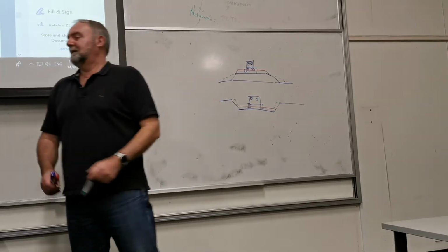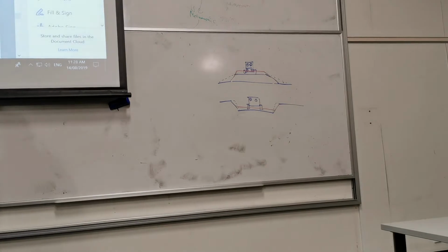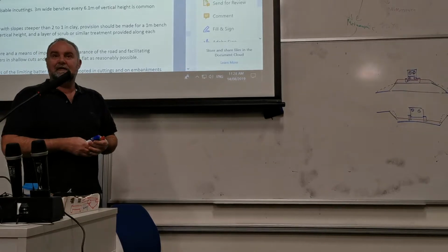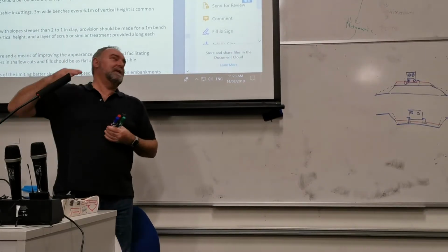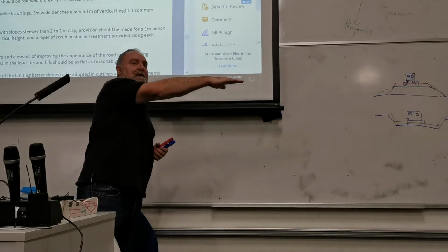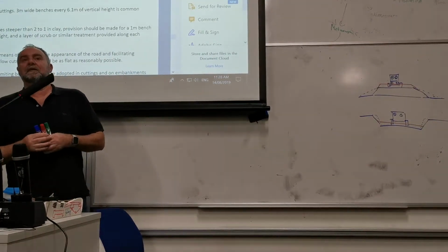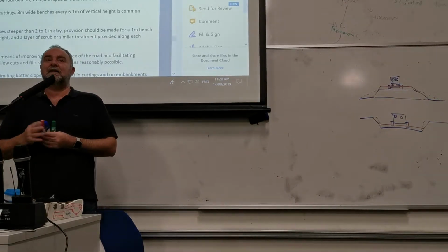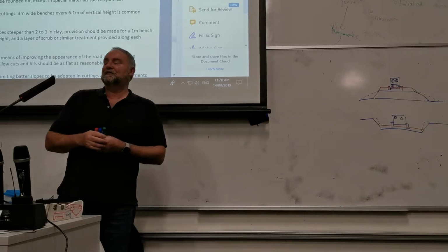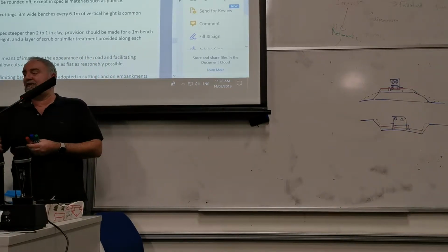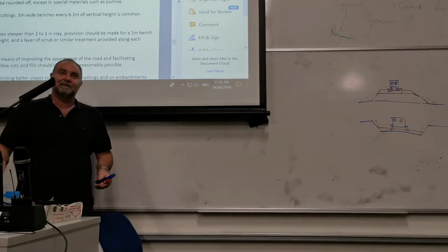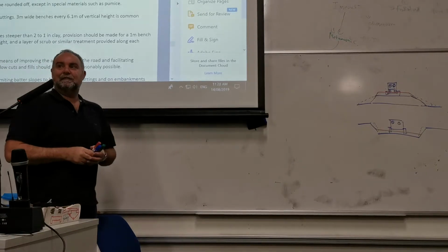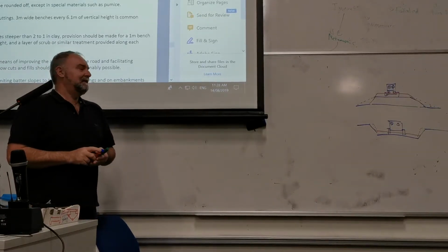And we used to do that all the time. We would do those different ideas all the time to balance our cut and the fill. Why? Because if you balance your cut and the fill along a road job, say it's 1 kilometre, you don't have to get the fill from anywhere else. You're using the same cut as you're going along the road. So obviously you need to plan it, so you cut first and then you patch up the areas of fill, then you cut again. But if you've got a balance at the end of a road job, you've done a good job, all right?